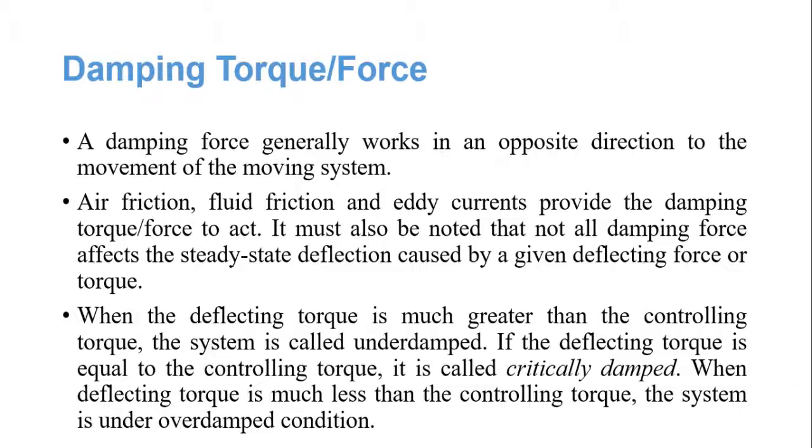So this medium provides the damping torque or force that is to act. It must also be noted that not all damping force affects the steady state deflection caused by the given deflecting force or torque. When the deflecting torque is much greater than the controlling torque, the system is known as underdamped. So there are three damping systems: underdamped, critically damped, or overdamped.